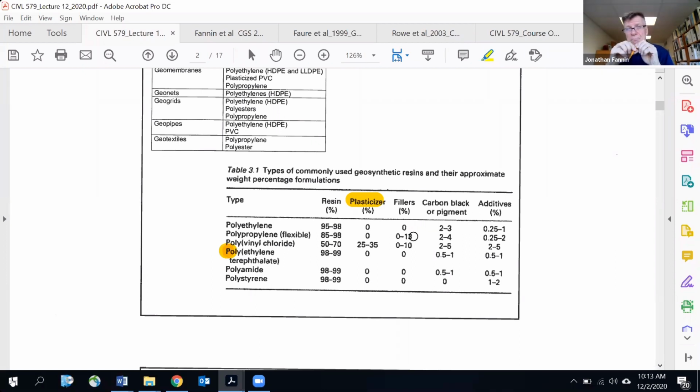to enhance durability. And the reason for that is that geosynthetics will tend to degrade, and degrade more aggressively, due to photooxidation, as well as elevated temperatures. And so the additives package, together with the carbon black, are the content that's introduced and will be extracted or leached over time more aggressively in UV light.